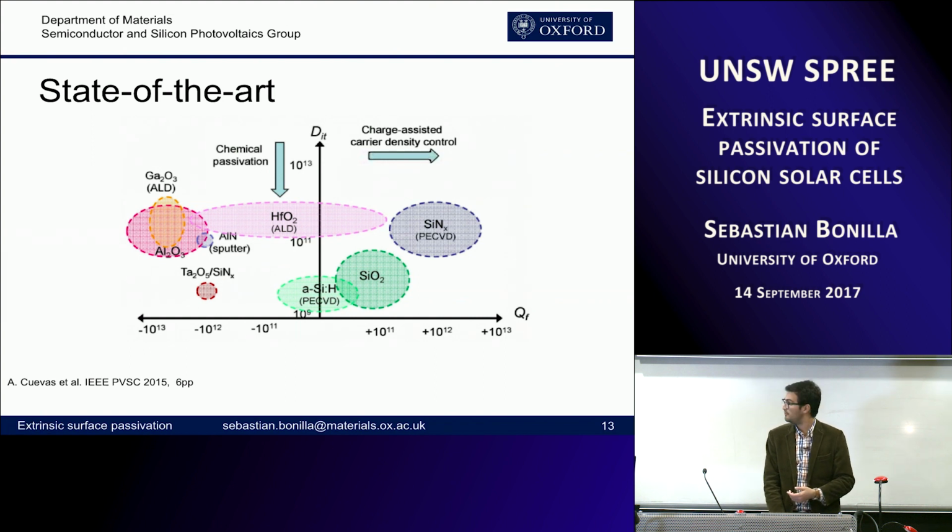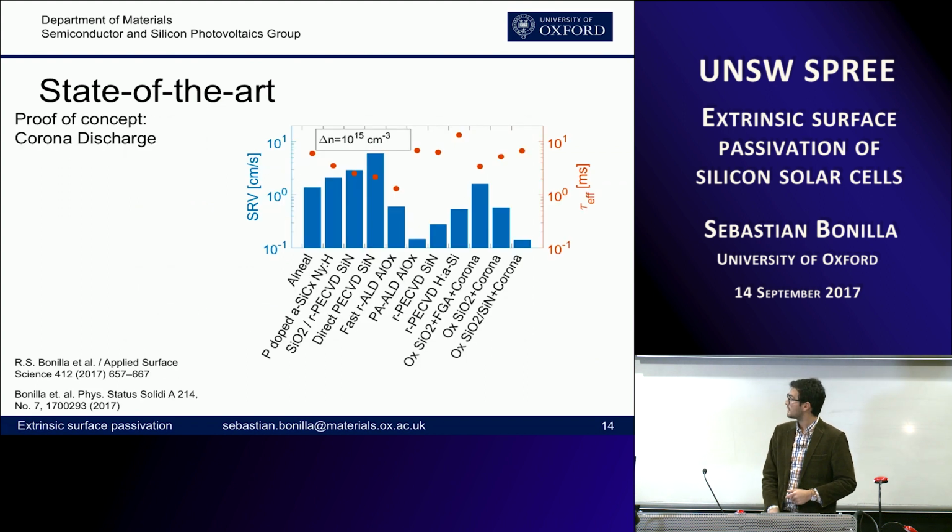So you can virtually change, if you take any of these coatings and you put more hydrogen into it, you could be pushing all of these down, or if you tailor the charge concentration, you could be moving them towards more positive charge and more negative charge in that dielectric. So that's actually a very versatile methodology to do what you want with your coatings.